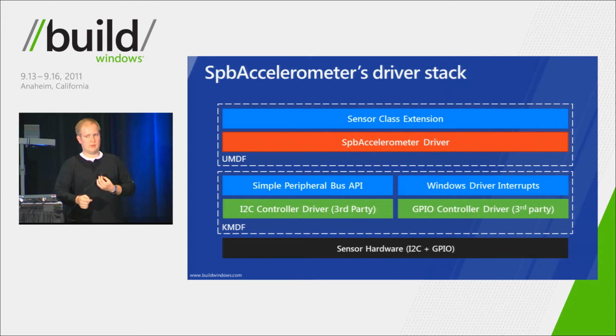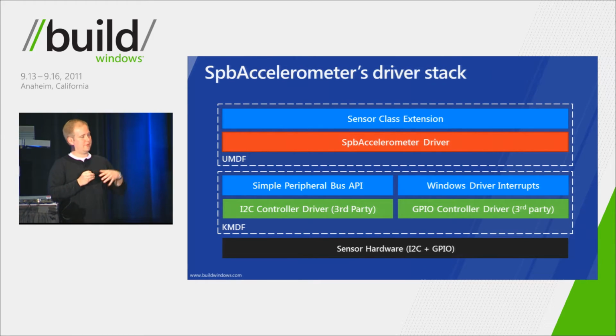We work with OEMs, ODMs, and part manufacturers to understand the characteristics of a given part. Something like 10-finger multi-touch at a very high sampling rate is going to be a lot of traffic. So we would encourage touch to be on a bus that has less traffic, maybe fewer devices, maybe no other devices. We work with PC manufacturers to provide that guidance.